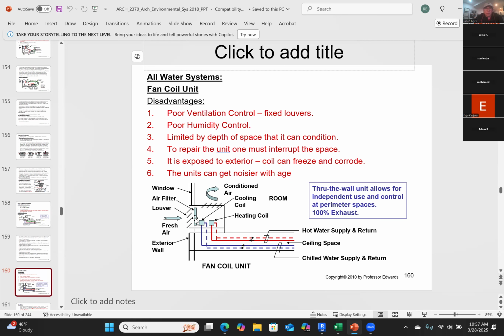The more fresh air we bring in, the healthier this air in theory would be inside the space. And the more fresh air we bring in, the more conditioning we have to do. And we know that conditioning costs energy, and we're trying to do both things at the same time. Make the air in the spaces as healthy as possible and use the least amount of energy, and they're conflicting goals that don't correspond with each other.